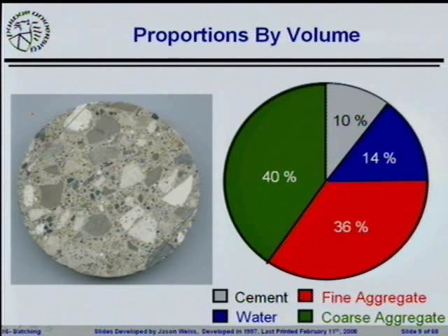So you'll remember we've got these different proportions, and remember, while we talk about proportions by volume quite a bit in this class, the only people who are excited about proportions by volume in large part are engineers. The reason we're excited about proportions by volume is shrinkage is going to be related to volumetric components. Compressive strength is related to volumetric components. You noticed when you had to estimate the compressive strength of a paste, it was related to the volume of the constituents inside of the material. When we have to talk about diffusivity, it's related to the volumes of the material. So all the engineering properties are typically traced back to volumes and the way that those volumes are connected together.